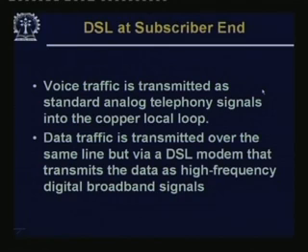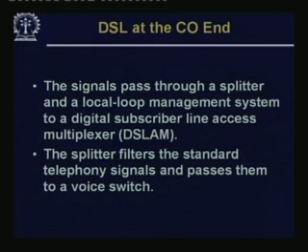So, DSL at subscriber end: voice traffic is transmitted as standard analog telephony signal. Data traffic is transmitted over the same line but via a DSL modem that transmits data as high frequency digital broadband signals on the same line. So, if you have a DSL modem, you can have both your voice as well as data at the same time, unlike very ordinary analog lines.